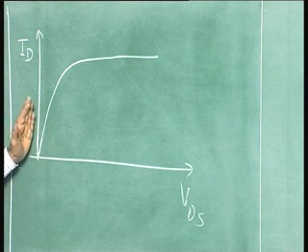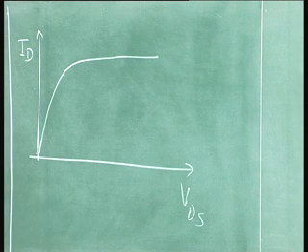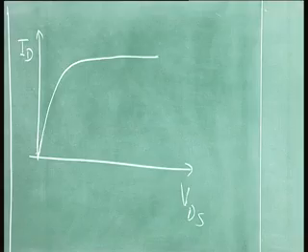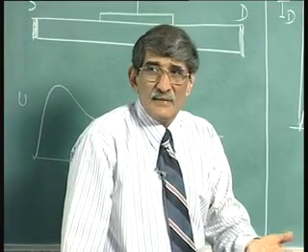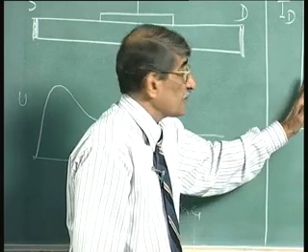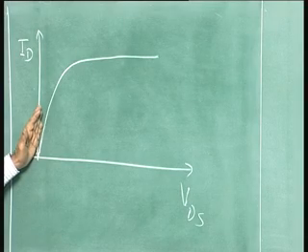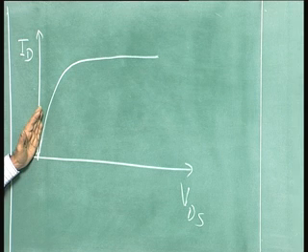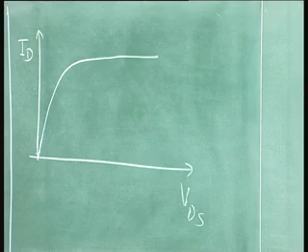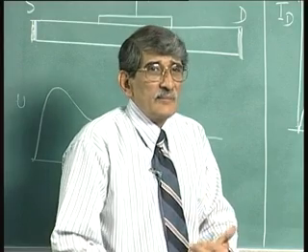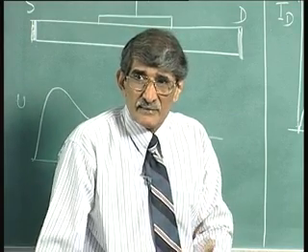From that point of view, you would like to use a device which has got high electron mobility. From that point of view, gallium arsenide scores over indium phosphide because of the high mobility. Gallium nitride, the material that people are talking of, is poor in that respect. Its mobility is not as high as that of gallium arsenide or indium phosphide, around 2000. People are improving on the quality of the material to get better and better mobility, the gallium nitride.